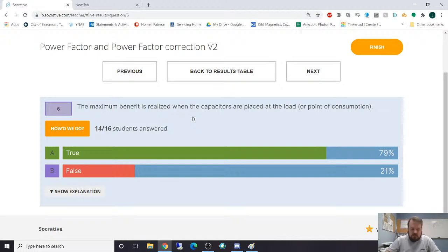So it will counter the load's induction every time the load is turned on, and whenever you turn the load off, it won't go the opposite way and cause a poor power factor because of too much capacitance. Because you can have too much capacitance whenever you overshoot your induction. But if you put it at the load, it'll always be on at the same time.